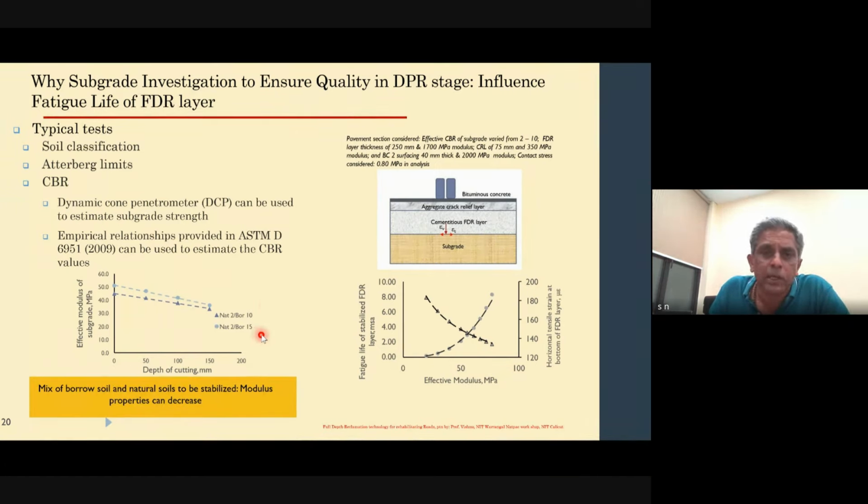In that one particular cement content, you vary the additive content, and then you go ahead and determine the OMC and MDD of that pulverized sample. You do the exercise for all the three different cement percentages. Again, the additive content would be recommended, or rather suggested, by the manufacturer of that particular admixture, and you have to go with that in terms of your mix design.